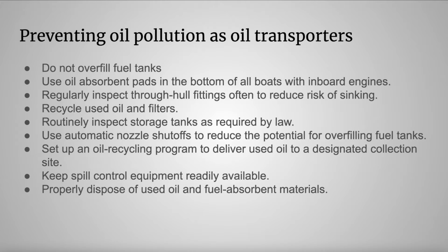Routinely inspect storage tanks as required by law. Use automatic nozzle shutoffs to reduce the potential for overfilling fuel tanks. Set up an oil recycling program to deliver all oil to designated collection sites. Keep spill control equipment readily available. Properly dispose of used oil and fuel absorption materials.